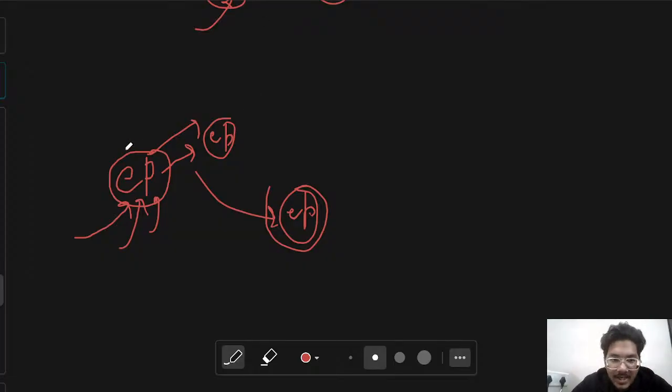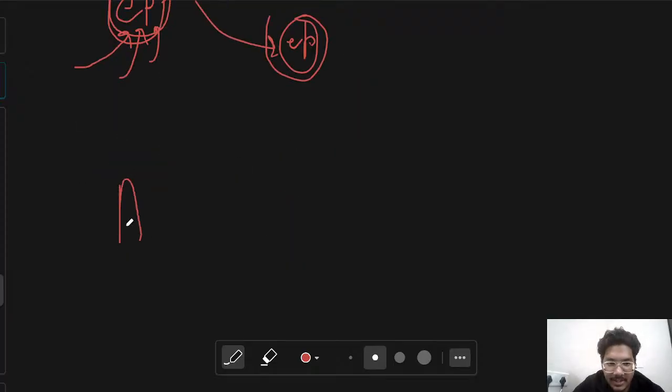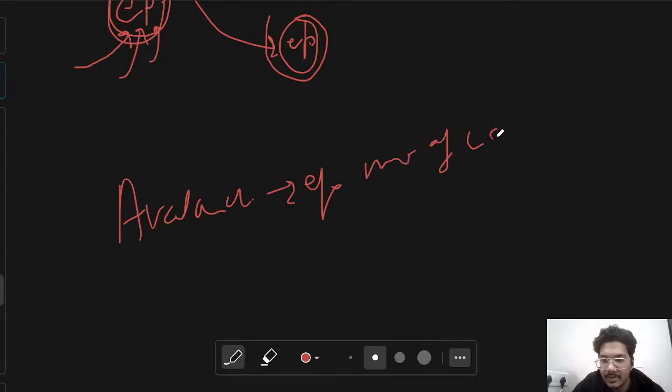As the carrier moves, the electron hole pair is termed a carrier. One electron can create several more, and these new carriers create even more carriers. This leads to an avalanche. The technical meaning of avalanche is exponential multiplication of carriers. This results in the internal gain.